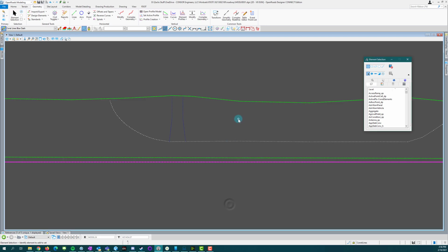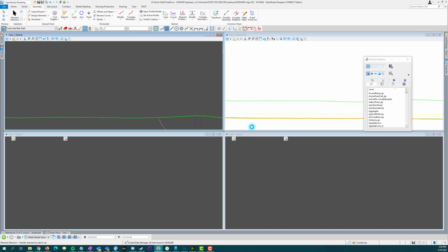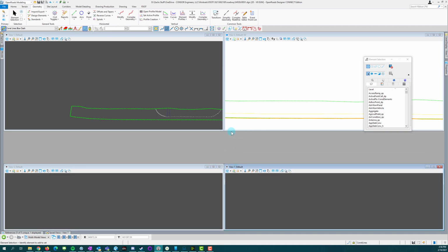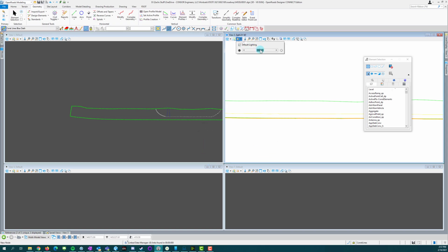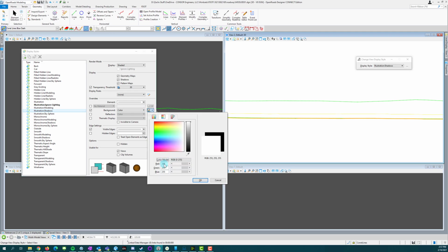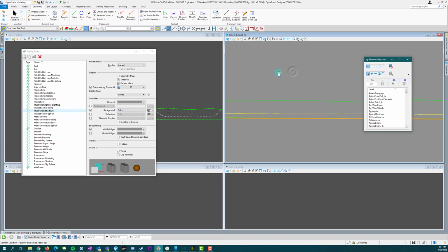So now I can turn my GDTM back on. It's already set as my active terrain model. I'm going to hit F4 here. F4 works in the FDOT workspace to open up these four different views. I usually like having a profile model and then a cross-section model, your 3D model, and your 2D model. And I can't look at this white screen. I have to fix that. Illustration shadows. Actually, what do I do? Just click in here and try and get near 140. Illustration shadows. There we go.